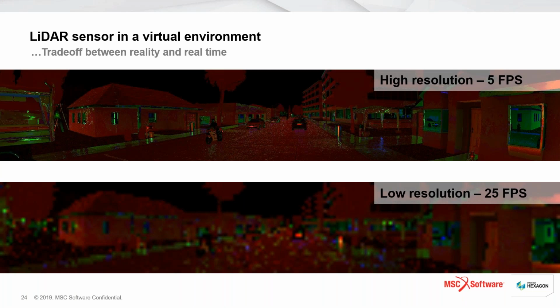In comparison to a camera, the lidar usually uses a much smaller definition in terms of pixels. You are not in a 4K pixel range, for example. So this allows us to use ray tracing for these physically based sensors, which is actually good for lidar, because for a lidar, you may want to take into account several hits and reflections, and you can have this information only with ray tracing technology.